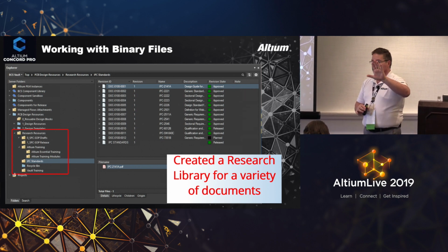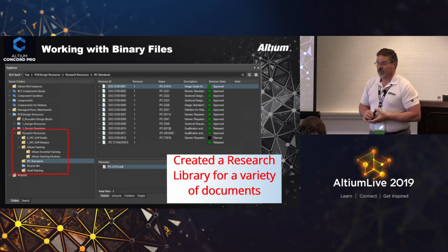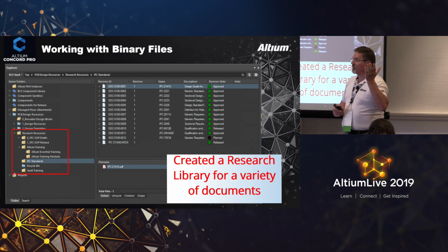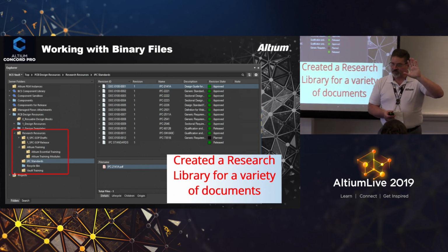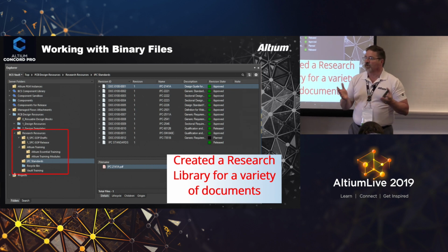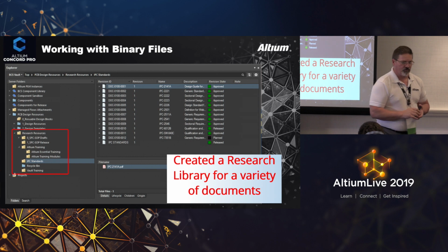They're all on your schematic as a symbol of a screw, and here is the parametric information for that screw. Because the symbol has no pins, what's the rule? Schematic symbol matches your footprint. We just simply have a 3D model that's pushed in. And it's a pretty cool method of doing it.